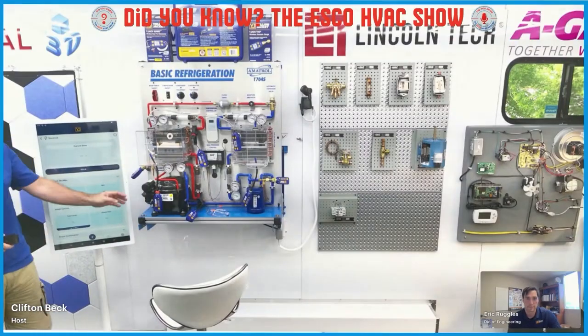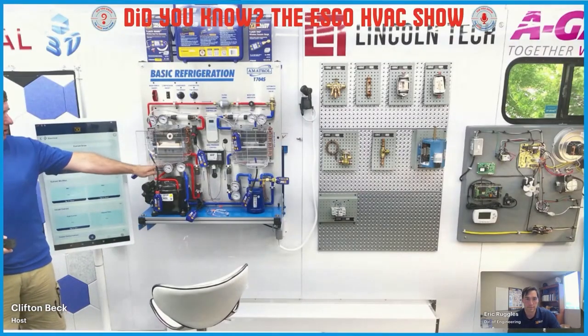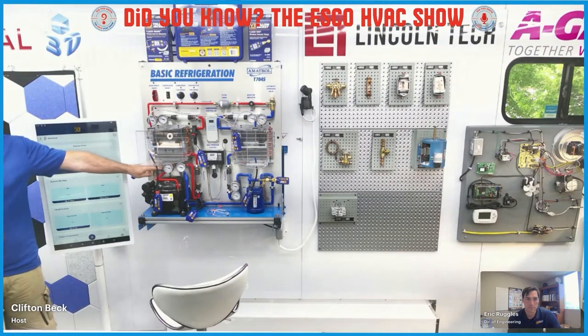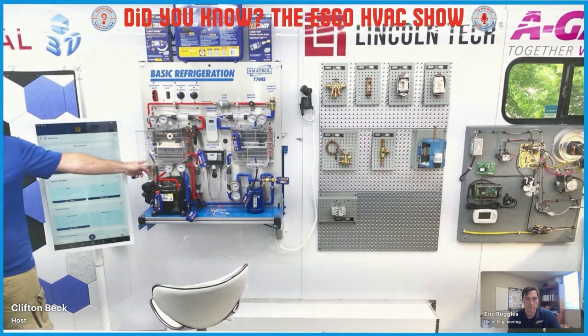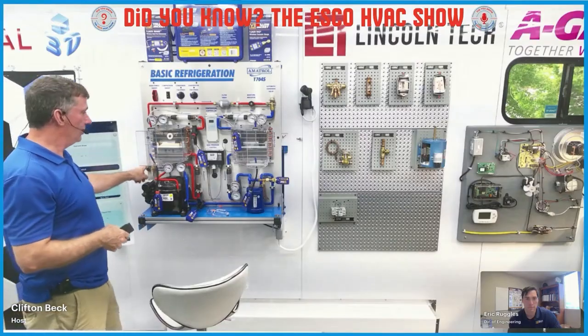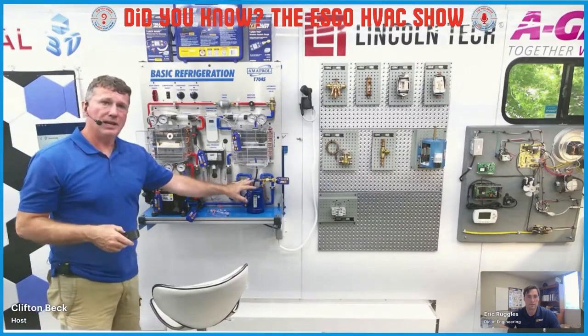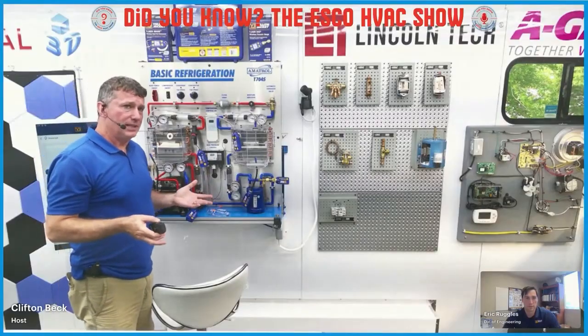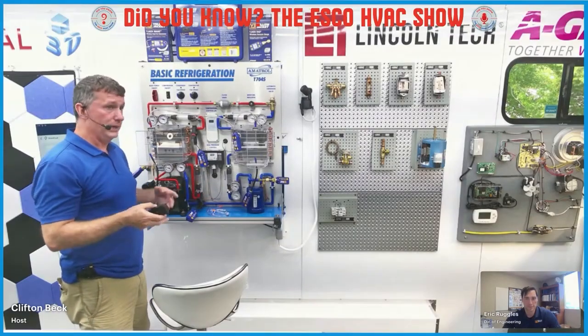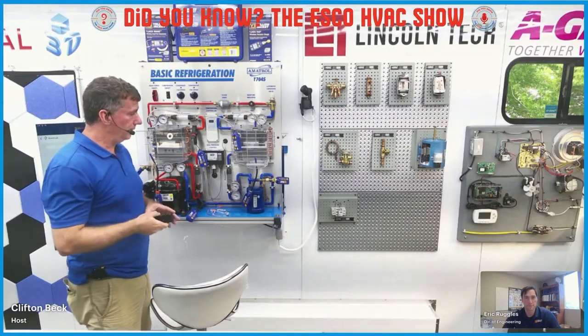Now we can see it. This particular one on the high side of our system is right here. So this had been our liquid side, and so we've attached our high side over here. So that's given us our low side pressure, our high side pressure, just like we were attaching a set of manifold gauges, whether it was a standard set or a digital.